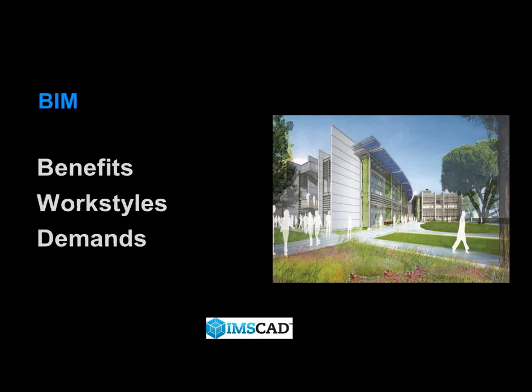So BIM, we're there. Now, I'm not going to spend too long in too much detail going on about BIM, because there's a lot of different levels and it affects a lot of different people in a lot of different ways. But in essence, let's touch upon the basics of it. Traditional building obviously was reliant upon two-dimensional drawings, plans, elevations, sections and the like. BIM extends this beyond the 3D, your primary spatial dimensions, width, height and depth. Fourth dimension, cost. Fifth dimension, obviously looking at time. So BIM is a process. It involves generation and management of digital representations of both the physical and the functional characteristics of a facility.